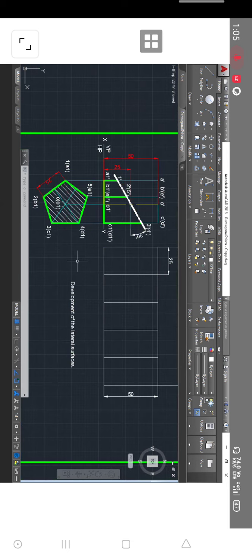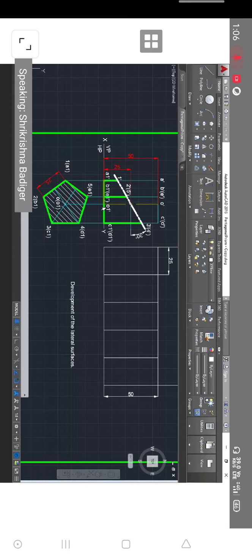So if you complete this much, you have completed the sectional top view. Please understand there are marks for various levels. If you just draw a simple pentagon, following one edge, the given condition, top view, and then front view, then you get a small number of marks. And if you show the section plane, where it is located, what the points are, and so forth, then you'll get some more marks based on your sectional front view. And if you modify this with correct hatching, you get the sectional top view.